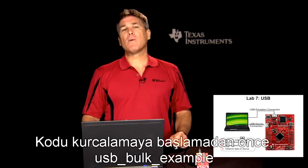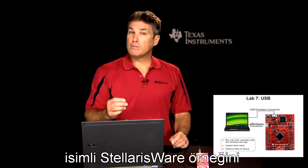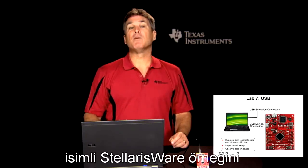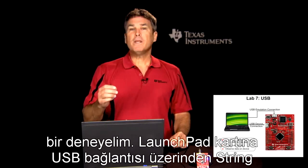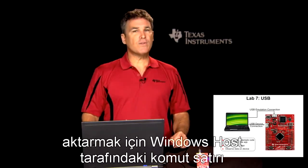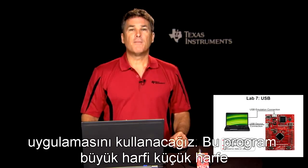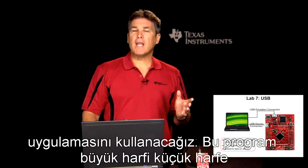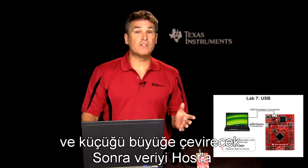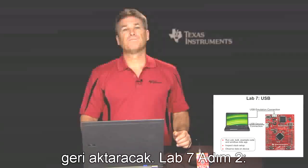Before we start poking around in the code, let's take the StellarisWare example called USB under bulk under example for a test drive. We'll be using a Windows host side command line application to transfer strings over the USB connection to the Launchpad board. The program there will change uppercase to lowercase and vice versa. Then transfer the data back to the host.